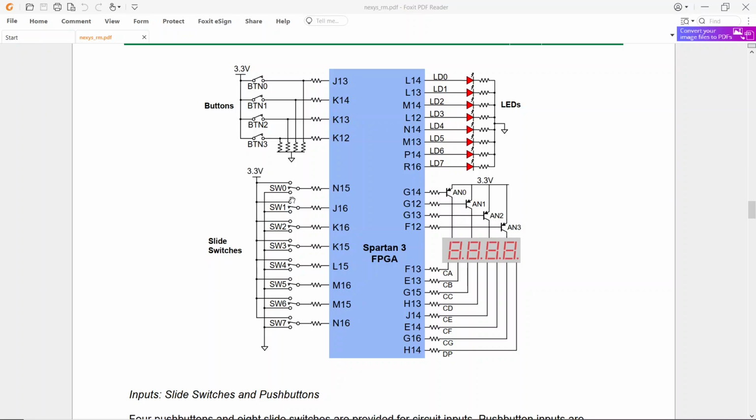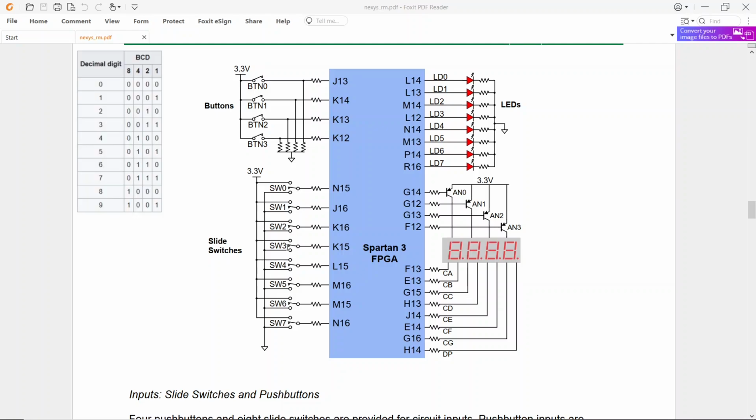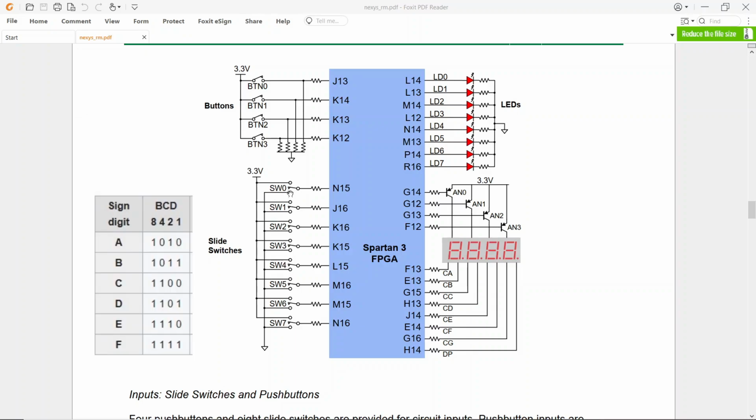And in this case, we can select, it's called a BCD, binary coded decimal. So if we set, let's say, 0, 0, 0, 0, the display will show 0. And then if we go for, let's say, 1, 0, 0, 0, then 1 is in the position of 8, so 8, or 1 1 1 1, which we do letter F, which is 15 in our representation.